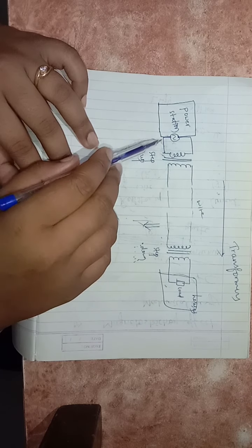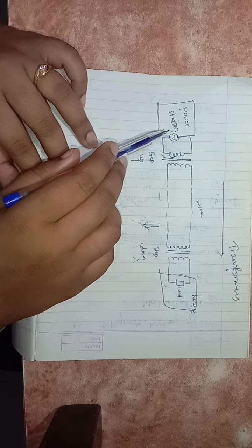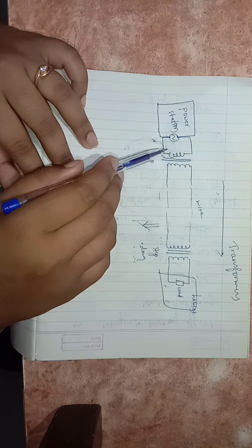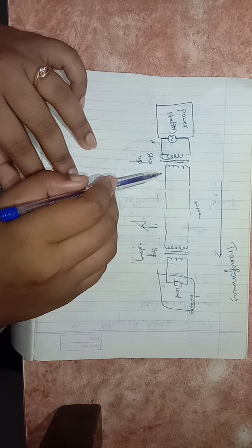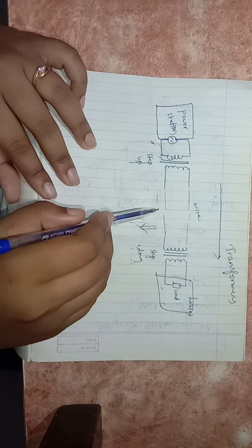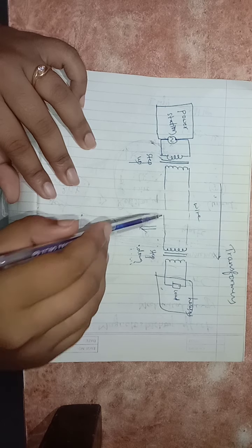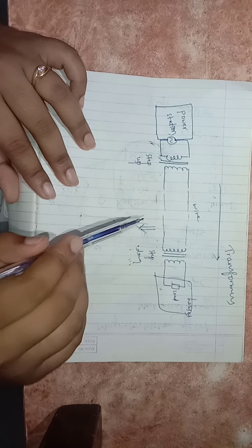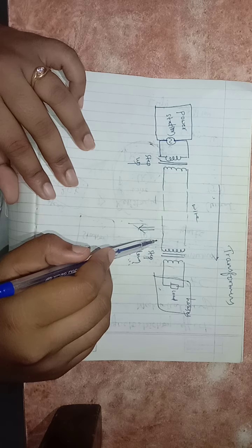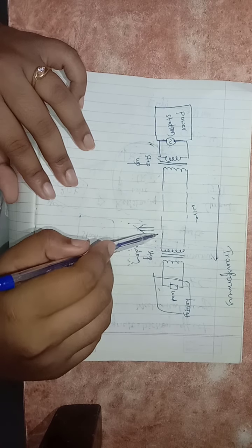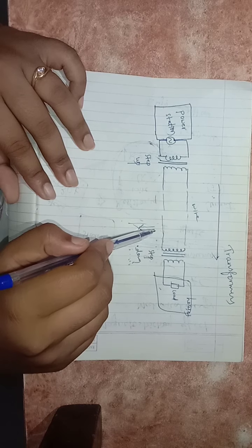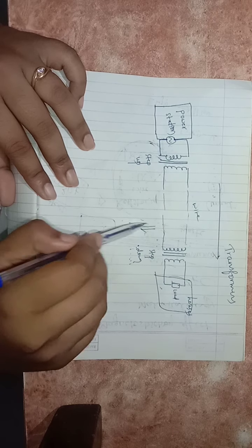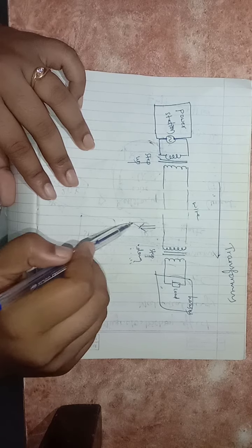The electrical power generated at the power station is fed to the primary coil of the step up transformer, and the output of the step up transformer supplies a very high voltage at low alternating current, and this low current at high voltage is carried by the transmission wire to the substation near the consumer side. Hence the power loss is very much decreased.